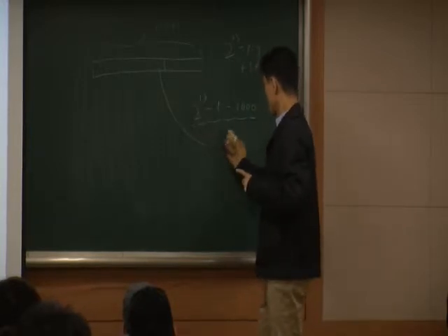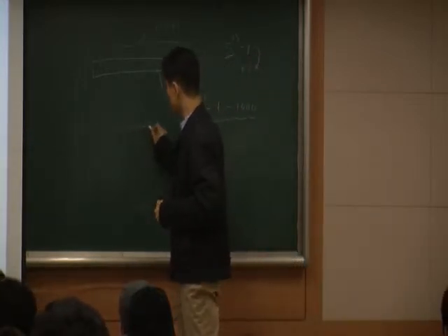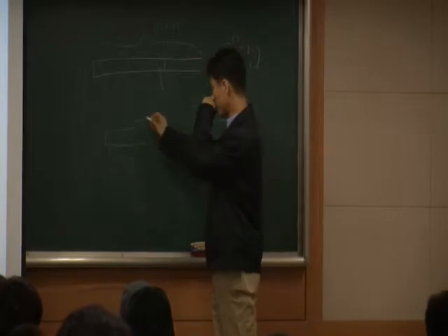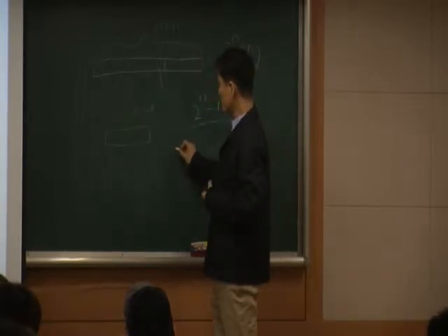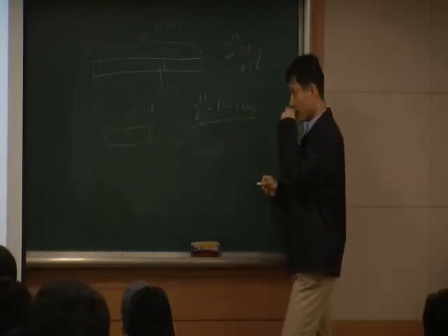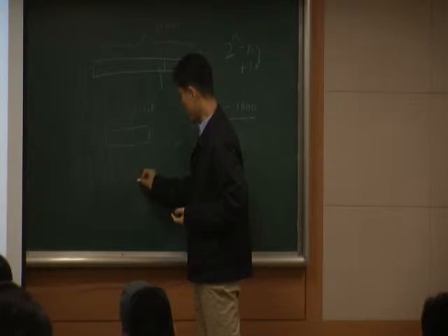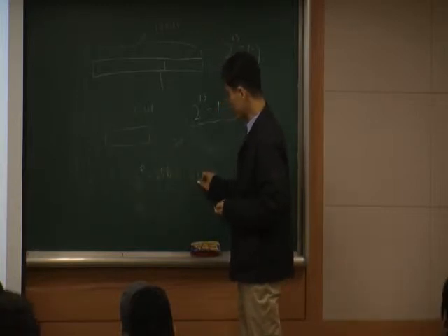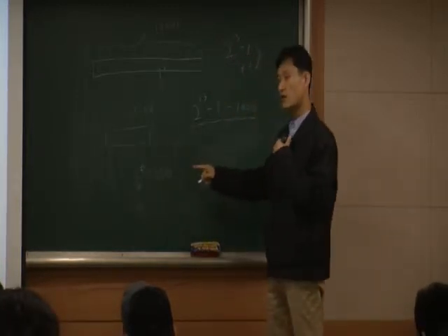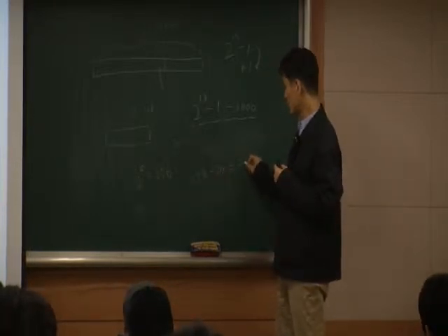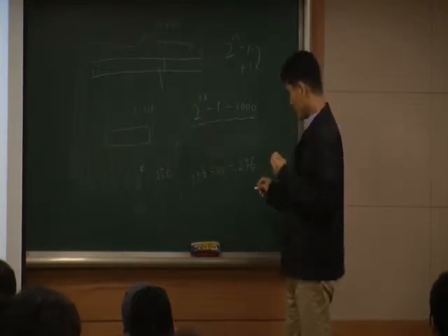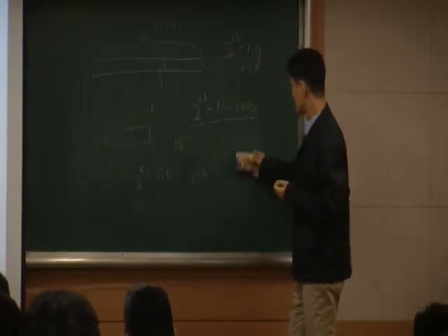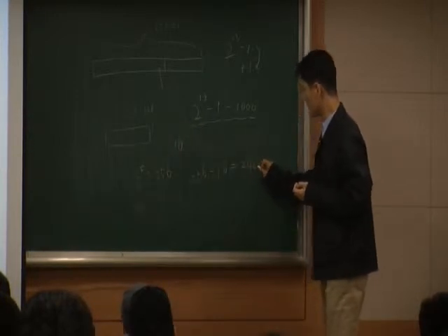Why is that? Let's pick a simple example here. Let's think about an 8-bit timer. Let's make a smaller timer, 8-bit. And let's say I want to count 20 pulses. In that case, the maximum value you can have with 8-bit is 2 to the 8, which is 256. What I'd like to have is 256 minus 20 because I want to count only 20 pulses. So 236. Let's make it 16, just to make it simple. In that case, 256 minus 16, then we have 240.